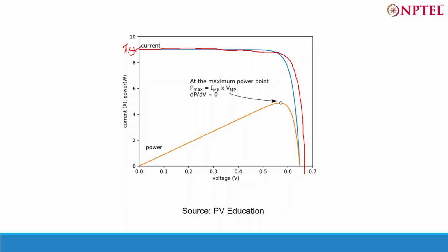And this is the open circuit voltage. What is open circuit voltage? It is the maximum voltage that can be obtained between two junctions of an electronic device, and short circuit current is the maximum current that can be obtained from the two junctions of the device. When can you obtain short circuit current? When you short the two junction points. And when can you obtain open circuit voltage? When you don't connect any load. That's why it is called open circuit voltage and short circuit current. So this is the ideal case.